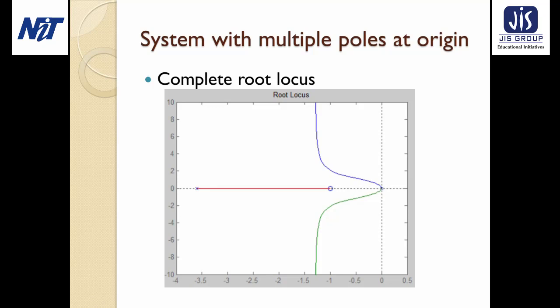In this way we can plot the root locus of the system, by varying the value of gain K. Root locus is actually the locus of the roots of the characteristic equation when the gain value varies from 0 to infinity. By varying the values of K, we can obtain the root locus, which is used to find the stability criteria in the field of classical control theory.